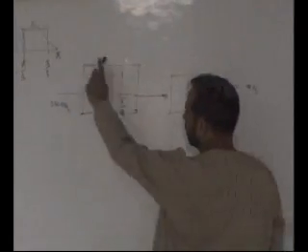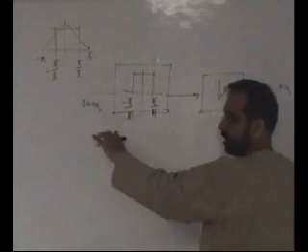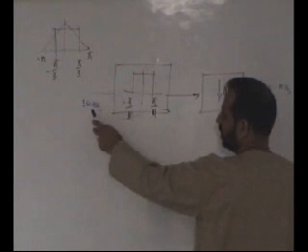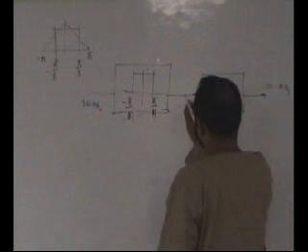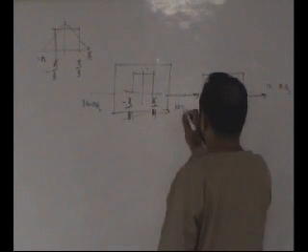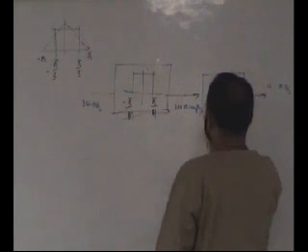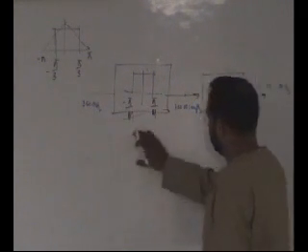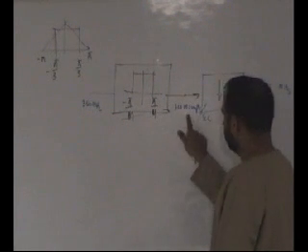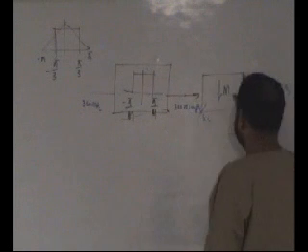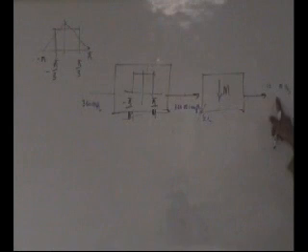If you compute this filter at the input data rate, you need to implement the entire filter to cater for 360 mega samples per second. So whatever hardware you have needs to work fast enough to give you this rate, and it is only here where you throw away these many samples to get to this rate.